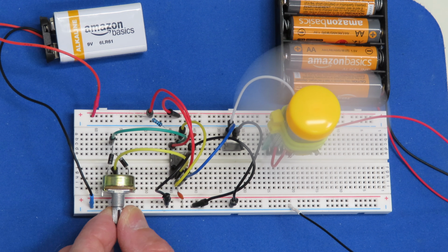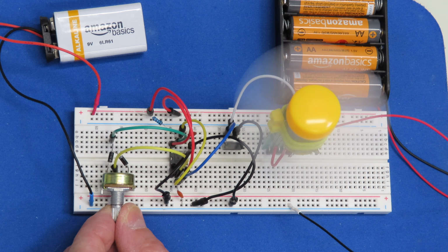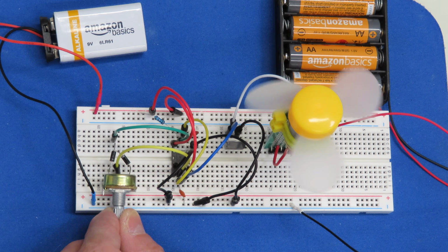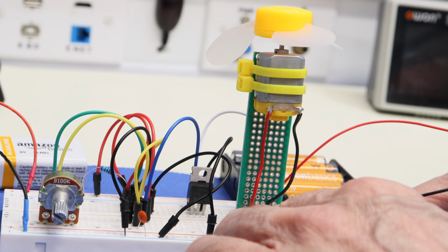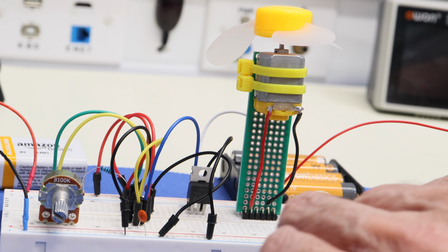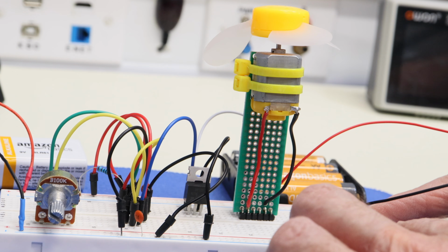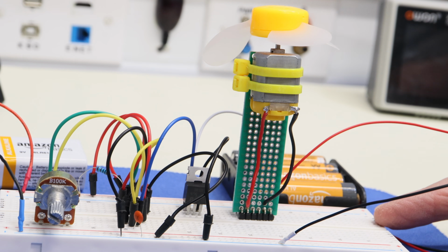And of course we've seen Arduino designs that use pulse width modulation that do the same thing. But once again, I want you to bear in mind the cost of the devices over here. We're using essentially the same MOSFET that we would use with an Arduino-based design, but we're using a very inexpensive 555 timer chip. And so this is a much cheaper design than an Arduino-based design. And if all you want to do is control the speed of a DC motor, this will work great.